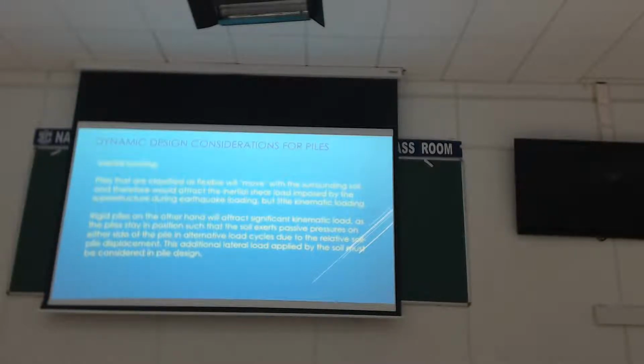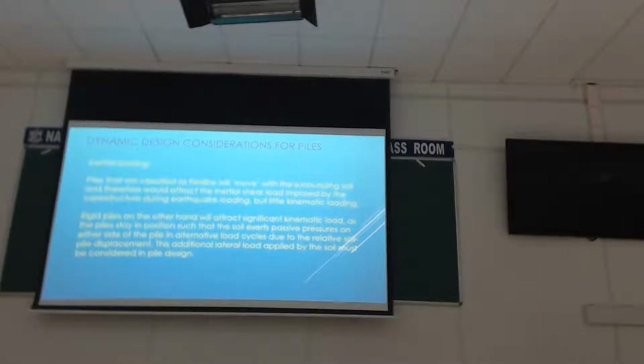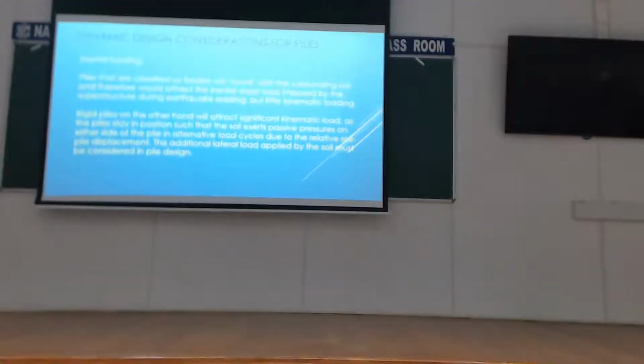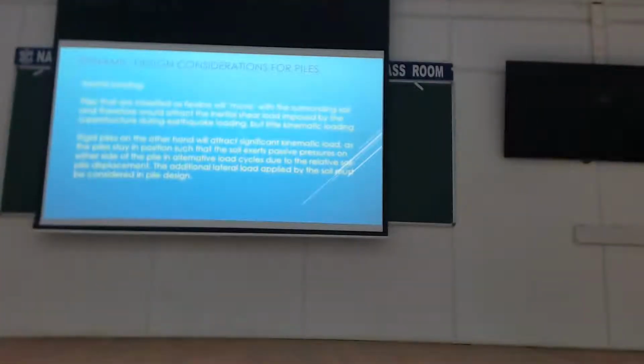So your shear forces are not going to be reduced because you're not mobilizing any interaction between the pile and the soil. However, your inertial loads, or the shear because of the inertial loads, will be high. Yeah? But the benefit you get, on the other hand, is you have almost no kinematic loading. Because you're moving with the soil, you attract no kinematic loads.